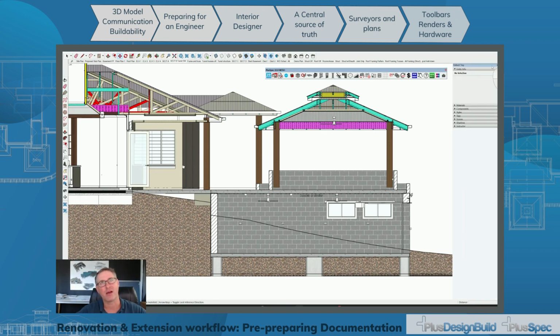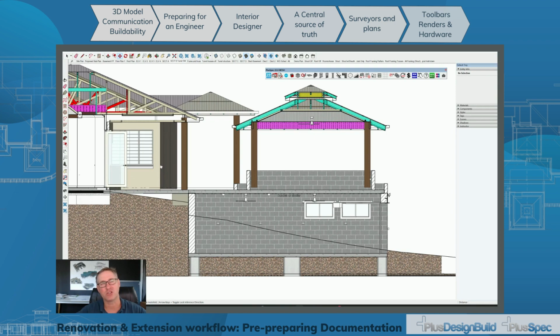I also have my default tray. Now, I'm using Windows, guys, and it is nice that you can dock it over to the side. If you're using Mac, you need to go to the Window menu, and you can select Entity Info, which is something I use all the time. And basically what Entity Info enables me to do is figure out what tag I'm actually on. So tags, you'll notice I have materials, which basically enables me to change colors. And if I was going to change this into a customer model, I'd probably select the material, edit the material, and turn the texture off and make it white or something like that. Right? So I use materials all the time. Components is where I save my vignettes, and you'll remember back in the first video how we went about using vignettes, but I also save bathrooms and kitchens and all of the things that I'll use again. I use the BIM tool so that when I bring them in, I already know what they're going to cost.